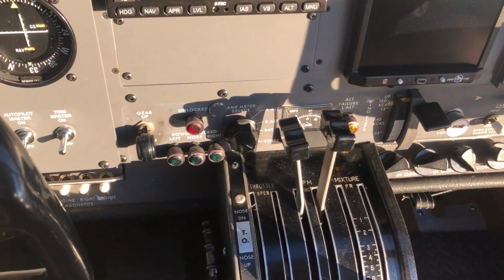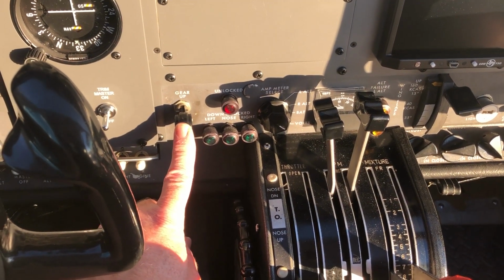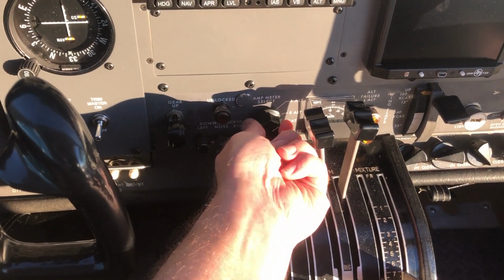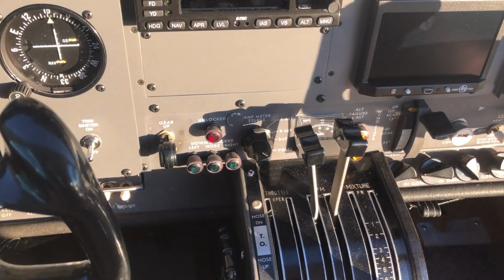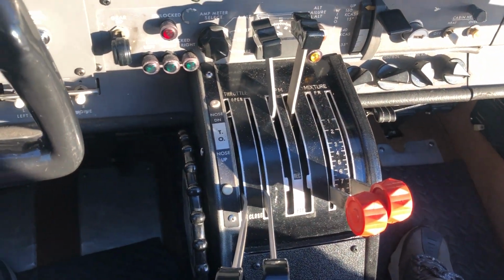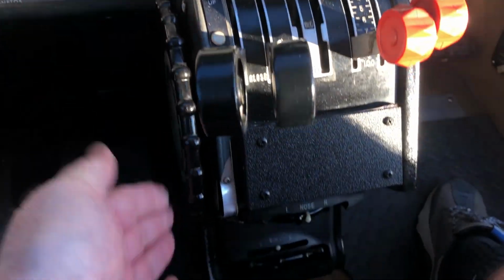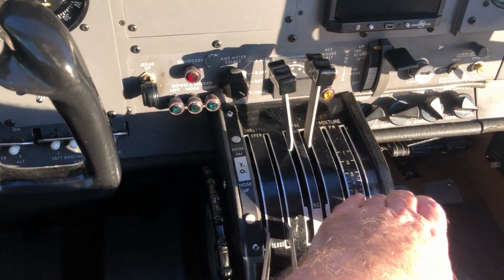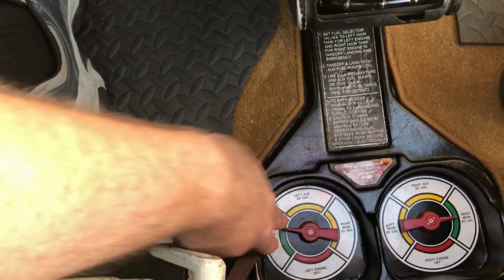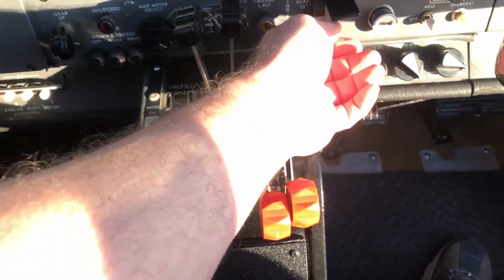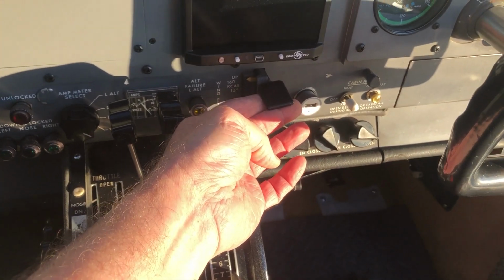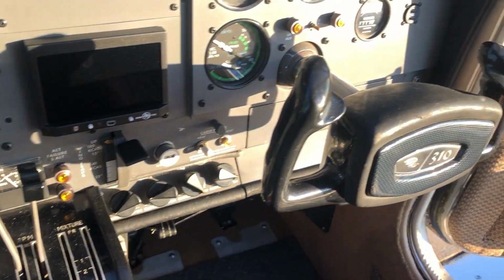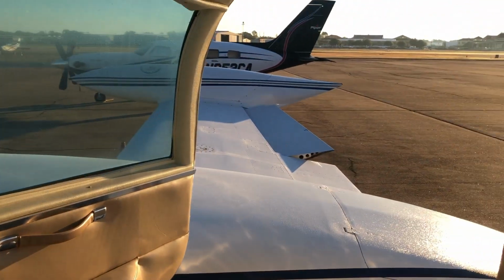Next, come over to the middle lower sub panel, check the gear is down. I go ahead and put my meter selector on volts, to check voltage when we start. Then I come down on the quadrant, I check all three trims set for takeoff. Throttles closed, props RPMs, mixtures idle cutoff. I come down and I check my fuel selectors on the tip tanks. My gear crank handle is stowed. My alt air switches are off, and then come back up and check flaps are up and cabin heat is off. And at this point I check my flight controls.